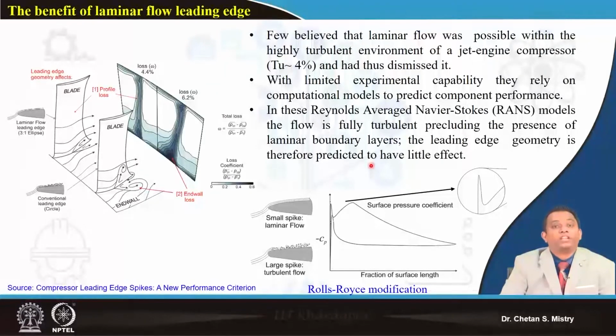So it demands a systematic study that needs to be carried out on what is happening on the suction surface. That is where our cascade tunnel comes into the picture. In order to study this situation in line with the Reynolds number we have, we need to select our chord length accordingly. We will be discussing this point because the chord length is very important for our design configuration also.